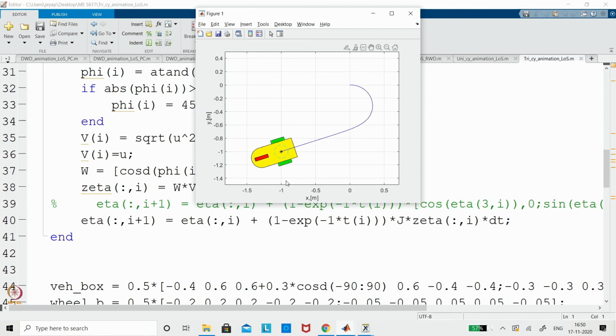Now what one can see is, if there is a W change, the further performance will get changed. That is what we are trying to discuss. All the combinations depend on only one thing, which we have derived as W. So now if you change the W, your wheel scenario or behavior will get changed. That's why you should know the non-holonomic and holonomic conditions. If the W matrix rank is 3, then you are safe, all 3 states are controllable. So that's what we wanted.